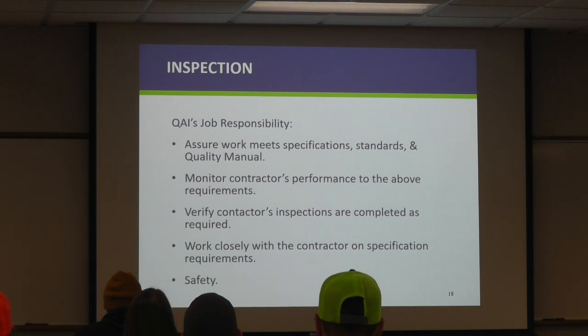We've pretty much gone from doing the actual field measurements and everything to just providing oversight. This has been basically pushed onto the contractor to provide how they're going to do it. I used to actually go into the containments, take all the measurements. I'd have my own notes, compare notes with the contractor. This is supposed to save time. So your assurance inspector is supposed to have knowledge of paint processes and procedures. You will make sure that the contractor is adhering to that quality manual and the specs.